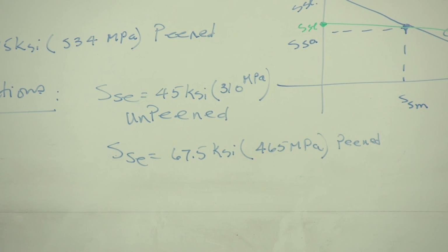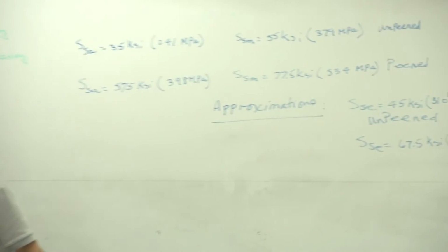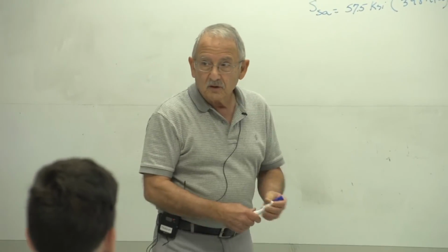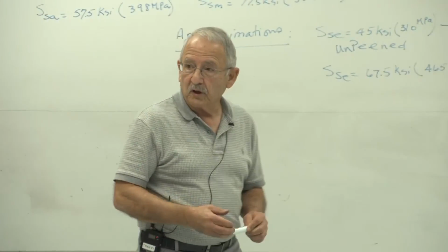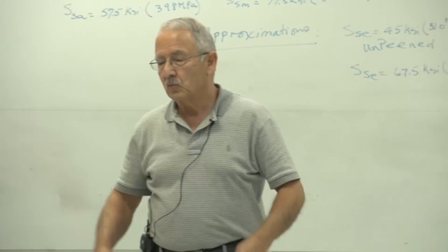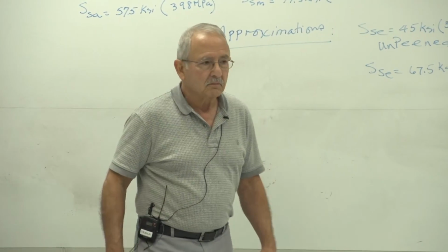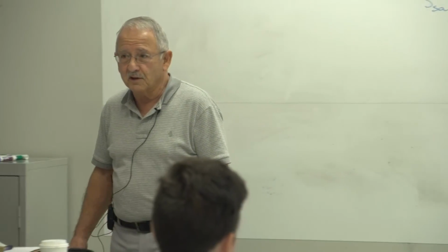So what exactly is peened here? Is it the material of the spring itself? What is peened? The wire. They peen the wire? Sure. Remember that the maximum stress occurs in the wire, right? How would they be shooting it at such a thin material? Before they form the wire. No, you have a wire, you peen it, you run it. It's very difficult to do it otherwise. I don't know, maybe somebody does it that way, but I doubt it.